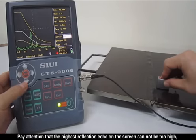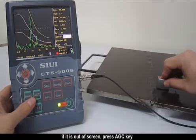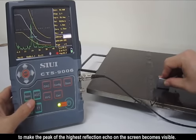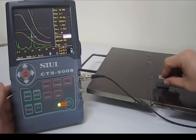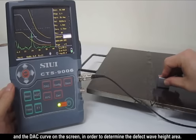Pay attention that the highest refraction echo on the screen cannot be too high. If it is out of screen, press AGC key to make the peak of the highest refraction echo on the screen visible. Read the defect depth D and size, and the relative position of the defect highest refraction echo peak and the DAC curve on the screen in order to determine the defect wave height area.